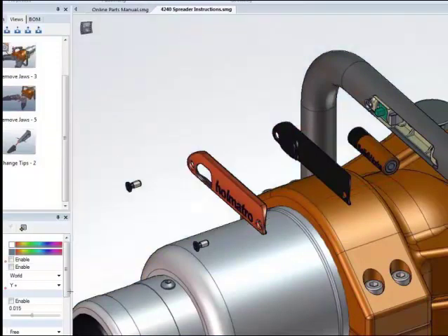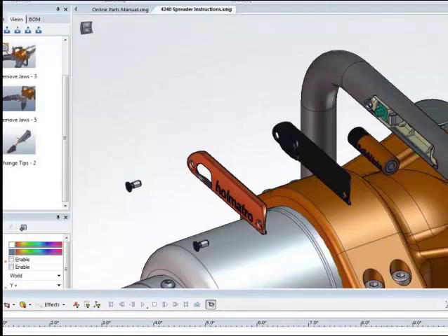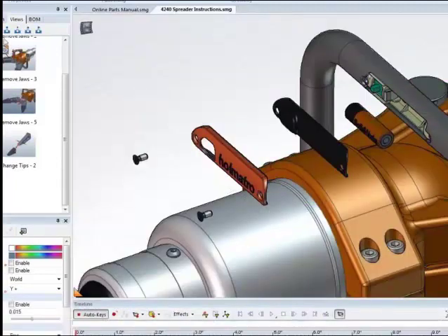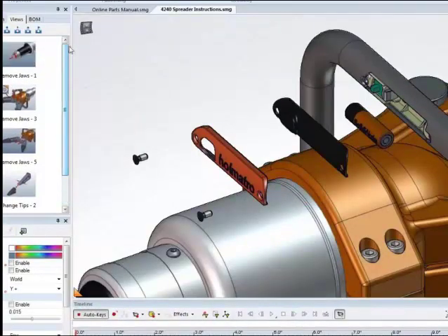Now, animations are very simple within Composer. This is all keyframe-based animations. So I can go ahead and change something from 1 second on the timeline to another, and it will capture what's happened between those changes. Now, we can also use the images that we have over here in our Views tab as what I refer to as more of a poor man's animation, but frankly, they can be used as the animation if you want to control this and then inevitably export this as an AVI file.